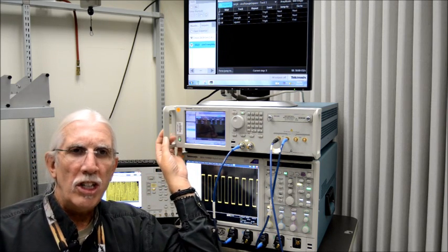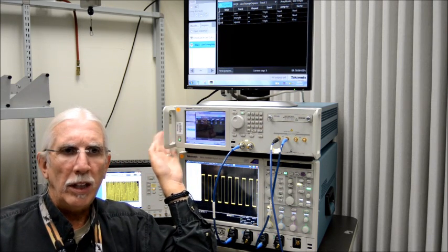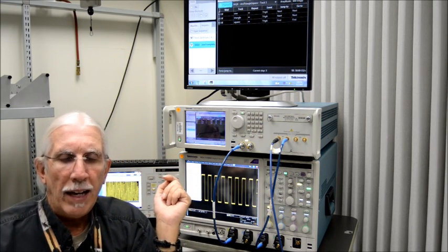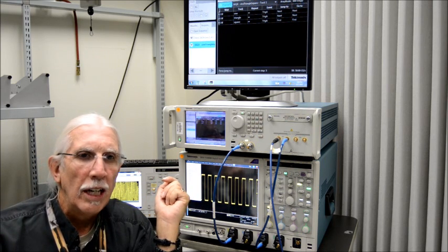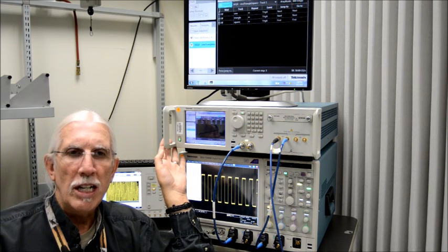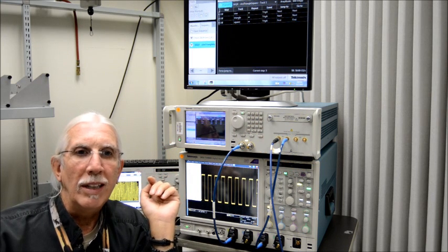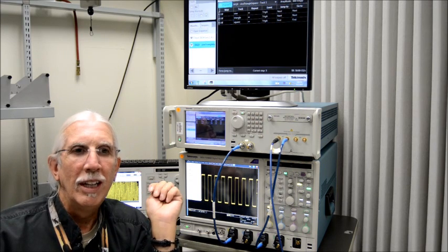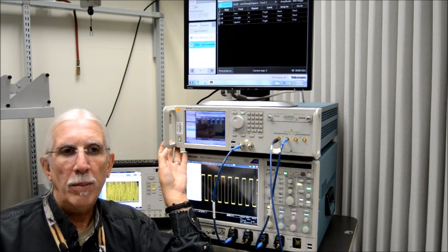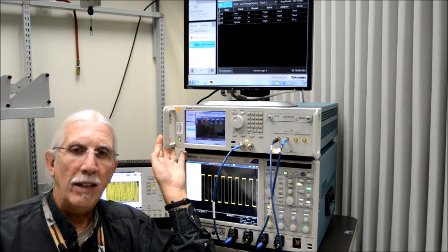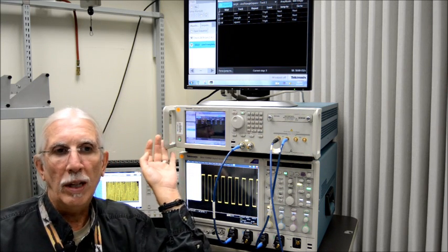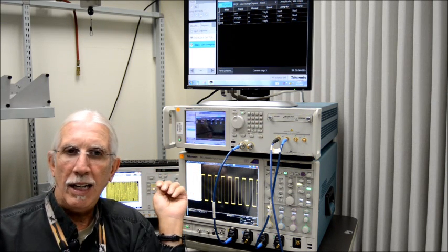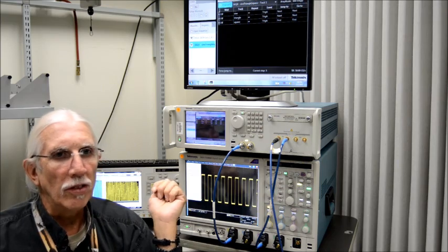This is a very general purpose tool, but it's really used in very high-end applications where you need to create waveforms that are very specific in nature. A lot of people use the AWG to duplicate real-world conditions rather than trying to go out in the real world and look at signals. We can create them on the AWG and provide that into your device under test to validate that your instrumentation or your product can indeed support real-world conditions.